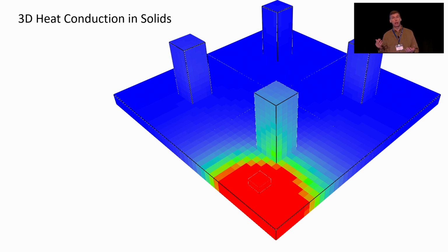And we know with LES, the gas phase time step is already pretty small, and to make that time step even smaller for the solid phase calculation would be prohibitively expensive. And in fact, as the grid gets finer and finer, this solid phase time step constraint gets worse and worse. So we had another idea to do this calculation using the same implicit solver that we use for the normal 1D heat transfer, the Crank-Nicolson updating scheme.